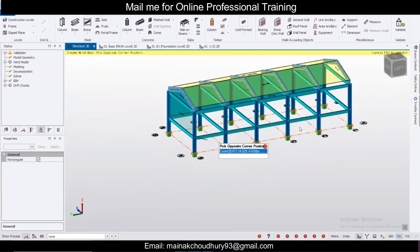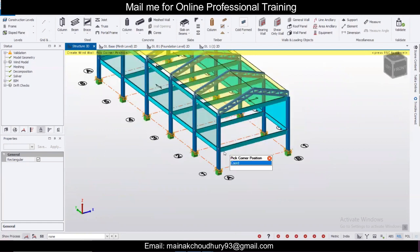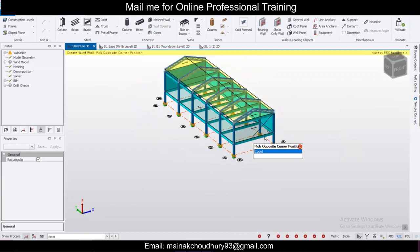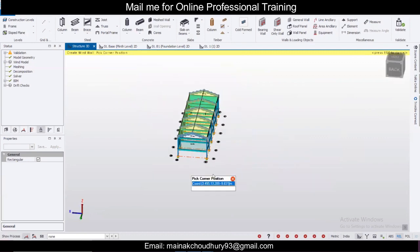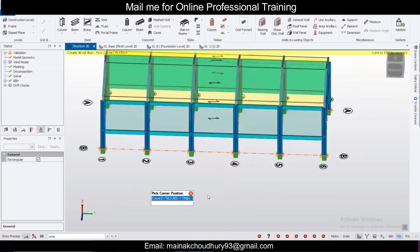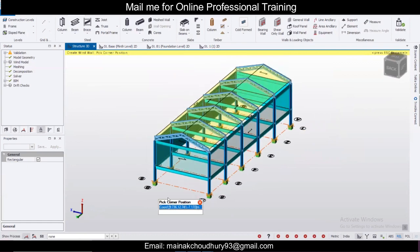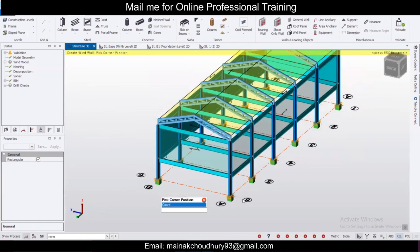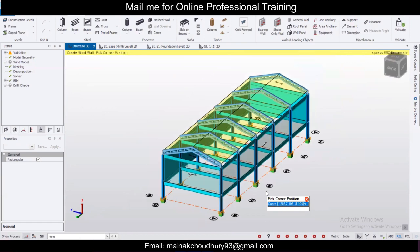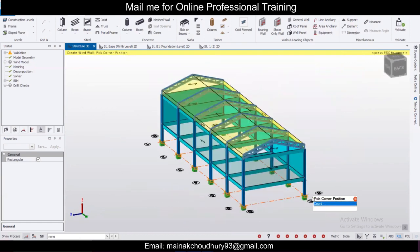Just use escape to go out. Escaped here, and this is the last wall panel. And obviously panels start from the plinth level. Below plinth level you never insert the panels here. So you can see to this point your modeling is complete, and the loading is pretty much similar to the other sections. You need to apply the loads and then go on to the design. So we'll do that in the next part and show you the results of the complete design.